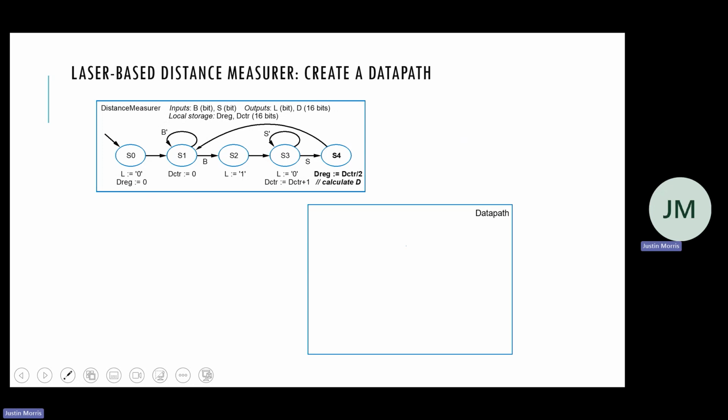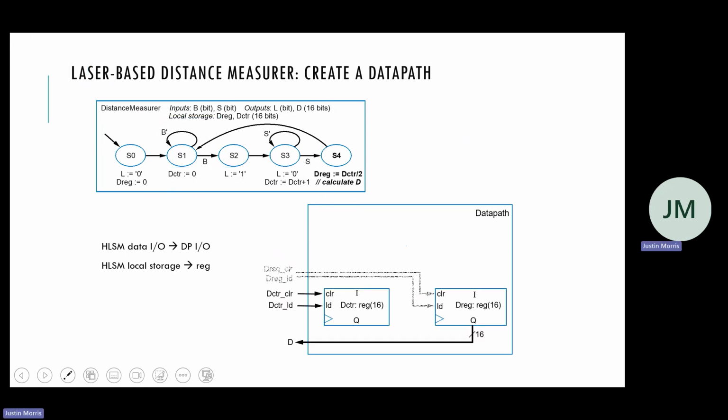How am I going to store them? What's it called? Yep, and a register is just multiple flip-flops, right? So I need 2 registers, one for counting and one for what is the calculated output. So here's my 2 registers. They have loads and clears, right? Because I need to be able to clear them. And then I also need to be able to enable them in order to get the new inputs.